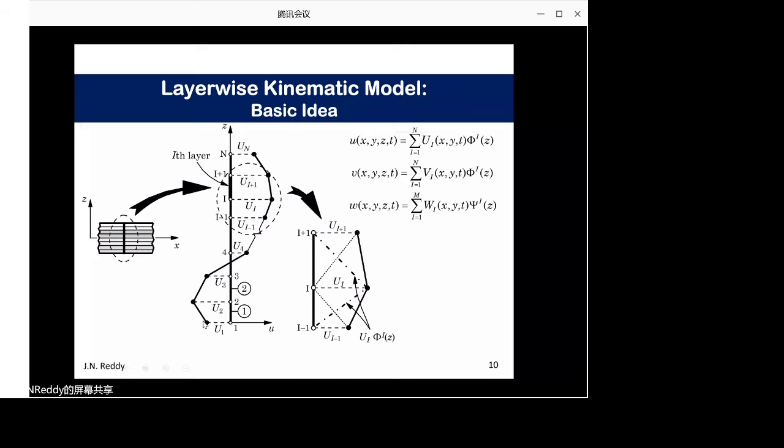That's what you see there. Whereas this one is a quadratic variation through thickness and quadratic variation in the XY. You see 3 nodes in X and Y direction means quadratic, and 3 nodes through thickness. So here all 3 directions are quadratic. Here one direction is linear, other 2 directions are cubic. So in the layer-wise theory, since we eliminate the thickness by assuming the linear variation to match this, you then have the cubic serendipity element in the plane. And here, quadratic through thickness and quadratic in the plane.